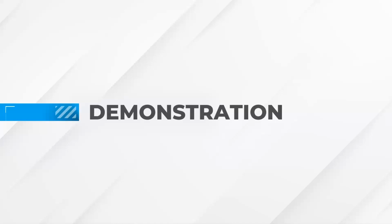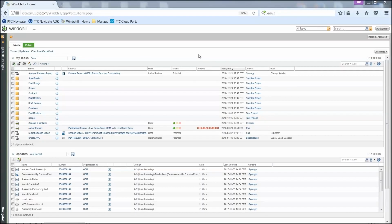Okay, so now we'll get into the demonstration portion, and what we're going to go through is understanding how you work from your engineering bill of materials to the manufacturing bill of materials, and then from that manufacturing bill, because you have all of the updated information, being able to create process plans directly from that bill of material on the manufacturing side.